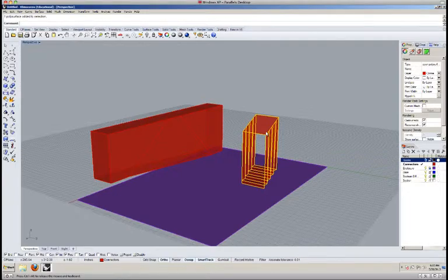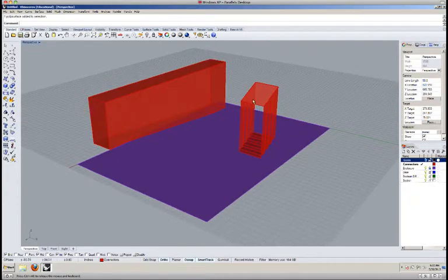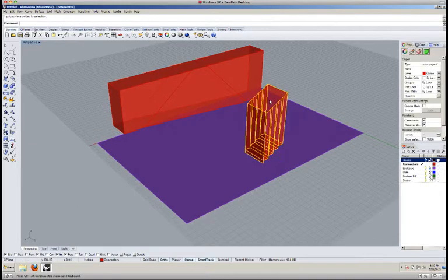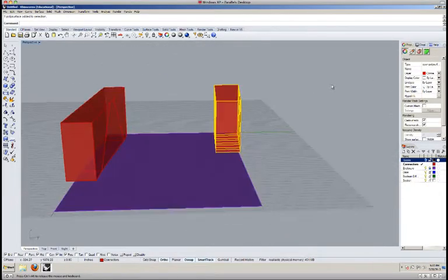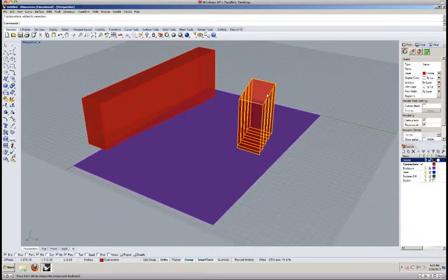So in the previous version, we used the loft command to make a surface on this face. So I can do that again. So LOFT. I can click this top edge and this poly surface edge. Enter, hit OK. Or I could take these two things and join them to each other. So I'm going to take this surface that's not connected and these that are, join.